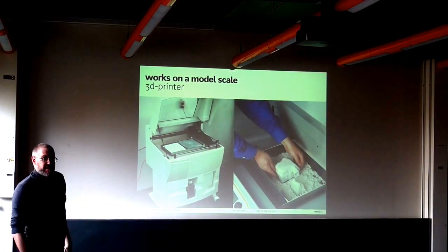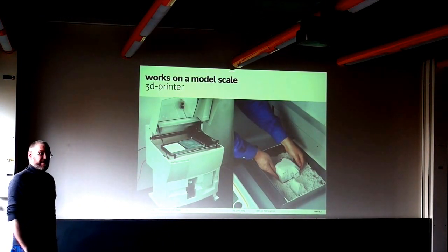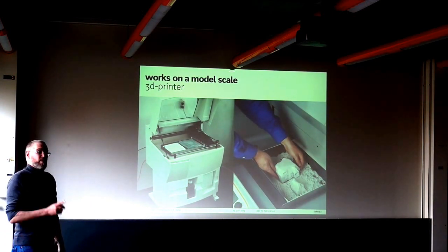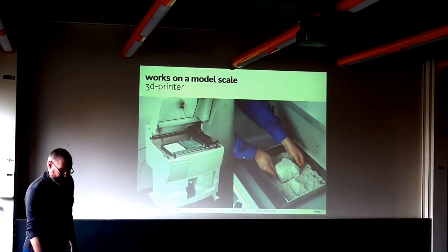Nice with homogeneous materials like this, nice with not more than 3 axes, because then you at least have not more degrees of freedom in the machine than you have in space, which makes things a bit more unambiguous. If you have 5 axes, there are infinitely more possibilities to get to one point in space.